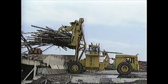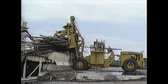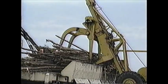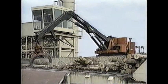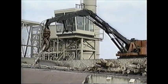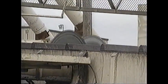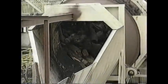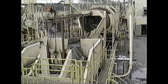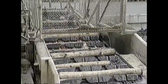With a mixture of tree length and log length material, the logs entering production first pass through an unscrambler, remotely controlled. The unscrambler sorts and places the logs so they are parallel to each other and oriented properly for the deck saws, which will cut them to 100-inch lengths. After cutting to length, the blocks pass through a drum-type debarker. Holding about 8 cords, the debarker allows continuous processing of 100-inch blocks.